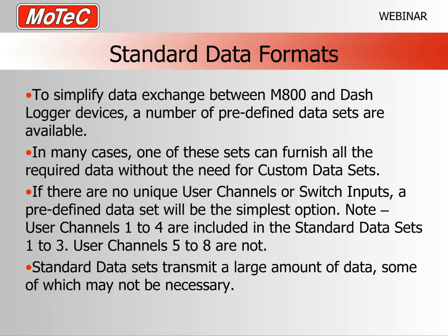So to simplify moving our data around, Motec has already created a set of standard data formats, and this allows us to more or less plug and play, whereas we can just select one of the standard data formats in both devices, and then the transmitting and receiving is more or less synchronized, and the data will appear in the same form in both devices. Now our data formats cover quite a lot of the standard data that's used between M100 series ECUs and dashes, and in that case it's quite possible that you can use one of our standard data formats without the need to set up a custom data set.